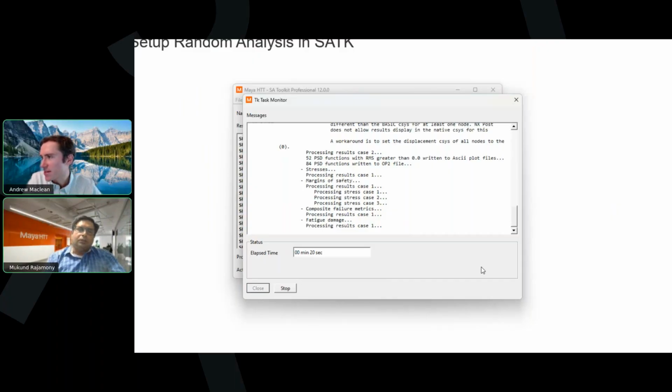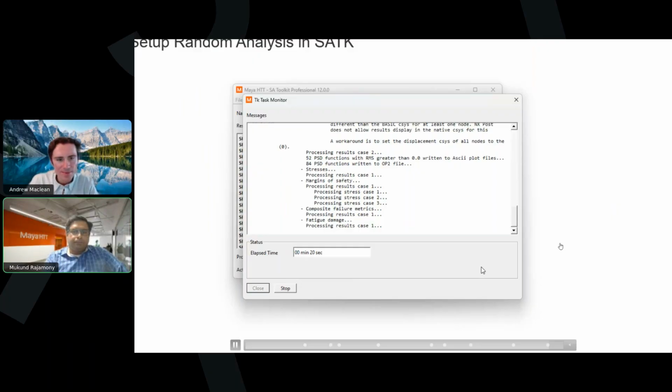Right. So typically, I think yes, you have to go above because random vibration is calculated most normally by superposition. If you truncate it too early, you'll miss dynamic amplification. And if you go too far, then obviously you're overdoing computational resource, right? So, yeah. Exactly.